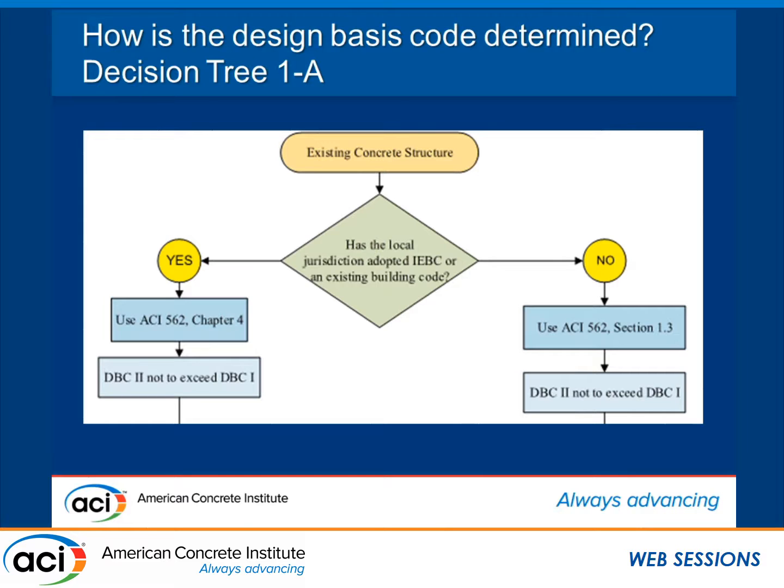The current building code, including the seismic maps and seismic provisions, have gone down. So we're currently dealing with loads for current provisions less than original design provisions of structures built in the 80s and 90s. So I'm going to give you a way to very quickly check this in a spreadsheet type scenario, and that'll be the last decision tree I take you through.